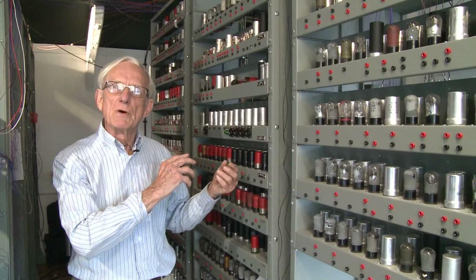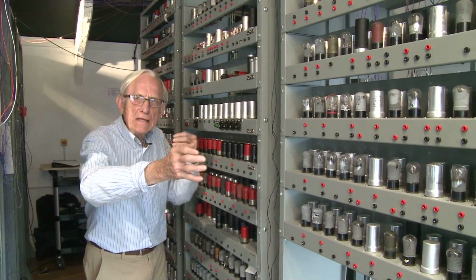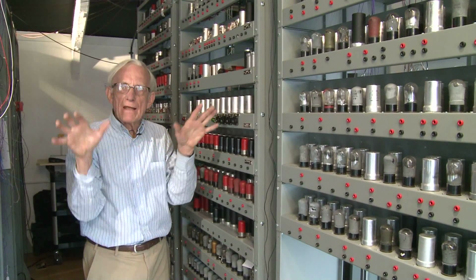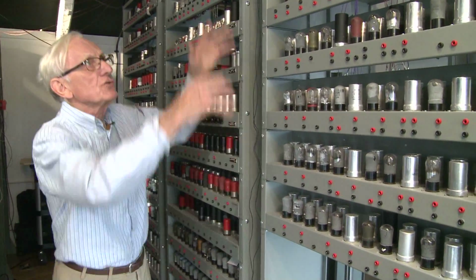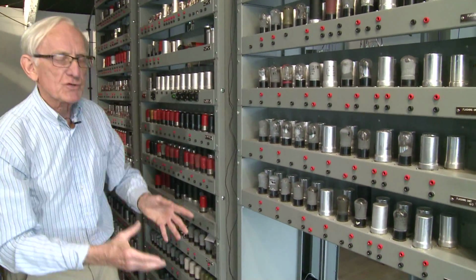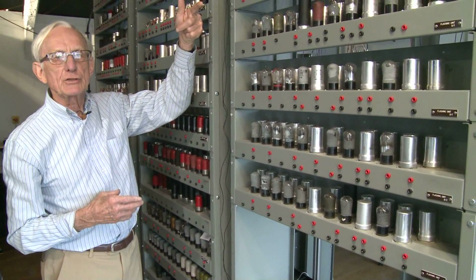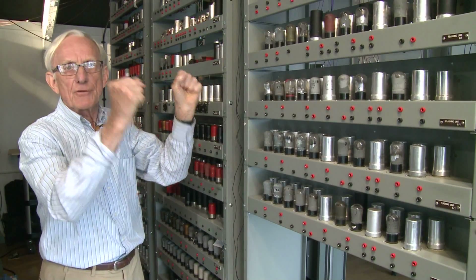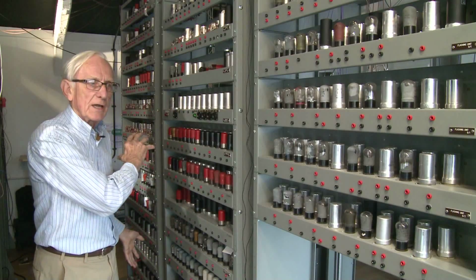So we have a problem of converting the serial stream of data on a very economical single wire into a parallel piece of data which is held steady. And this rack here holds the static units which are fed with serial information from the memory tanks, for example, and then hold that for the 72 microseconds or however long it takes to control the gates.